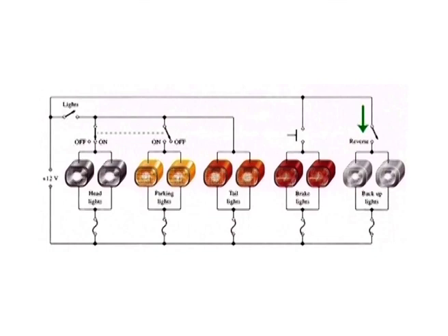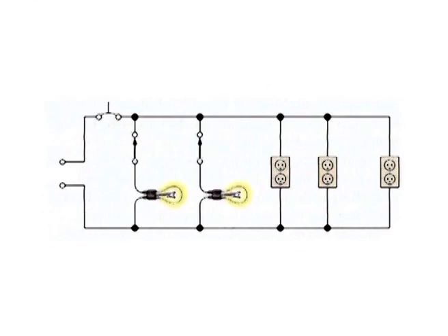The backup lights are switched on when the reverse gear is engaged. Another common use of parallel circuits is in residential electrical systems. All the lights and appliances in a home are wired in parallel. The figure shows a typical room wiring arrangement with 2 switch controlled lights and 3 wall outlets in parallel.